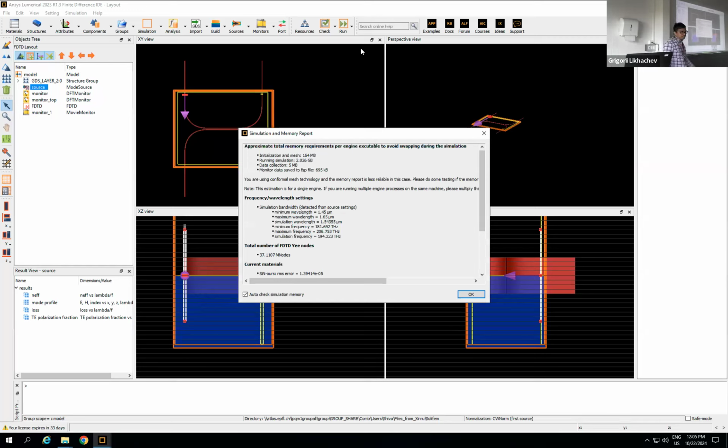You have 100 wavelengths and 100 refractive index values, but then your spectrum was broadband from 1.4 to 1.6 micron. What you would need is the refractive index for any value that you would like to simulate. So you need to do an interpolation of this refractive index, which we didn't do, which I will just show how to do.